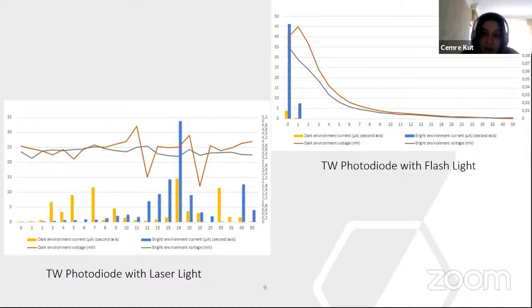We saw a value of 190 millivolts in a bright room light without laser light. The values in the room light were very variable because we took an average value. This is because the ambient conditions, the sensitivity of the photodiode and the incident light are constantly changing.